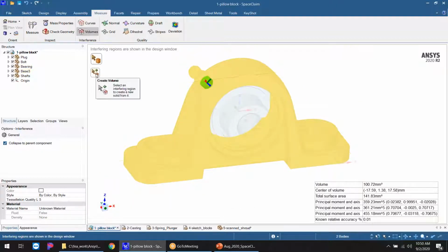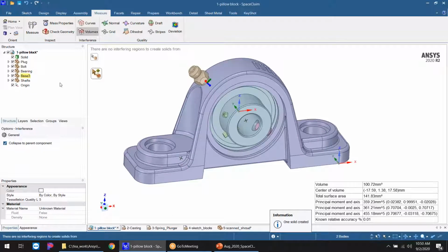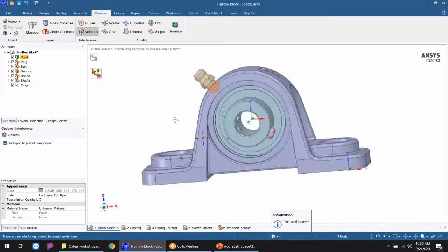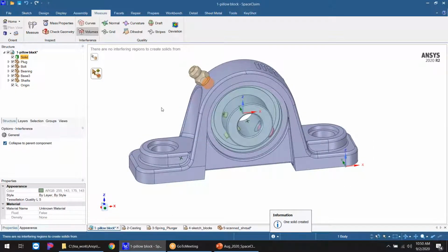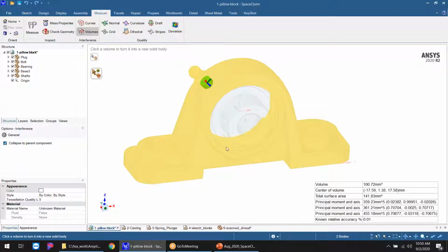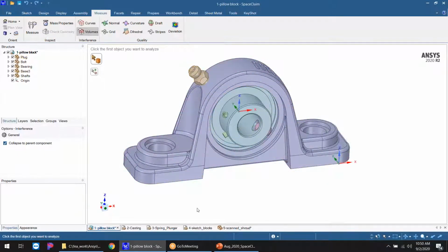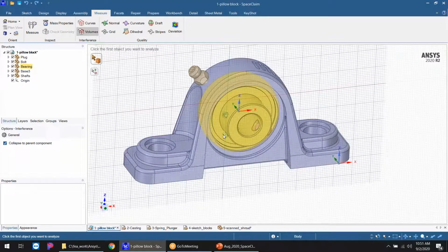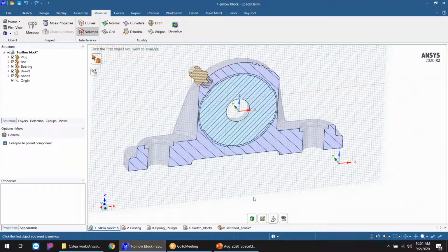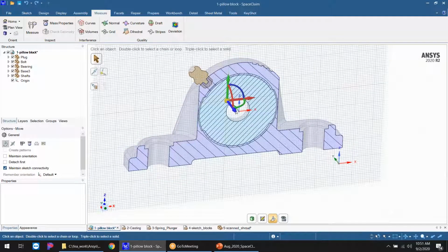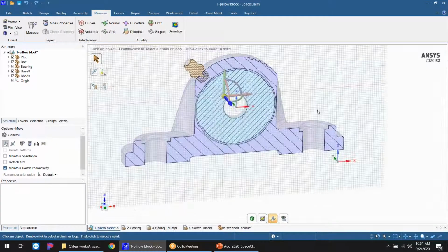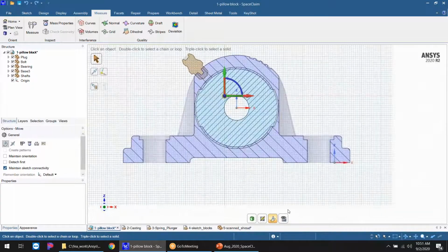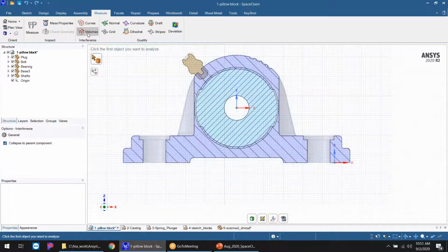From this tool, you can actually create a separate volume from that. So if I click on the interference, I actually just added that. That's not the most helpful, and not probably a typical workflow. A more typical workflow is, how do I remove that interference? So what I'm going to do is go back into cross-section mode, grab this, and move it back just a few. It looks like we're already in the middle. Fantastic. Go to 2D, go into my measure, go to volumes.